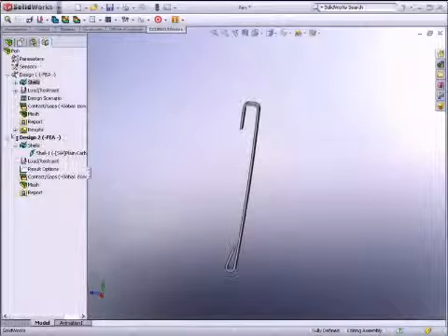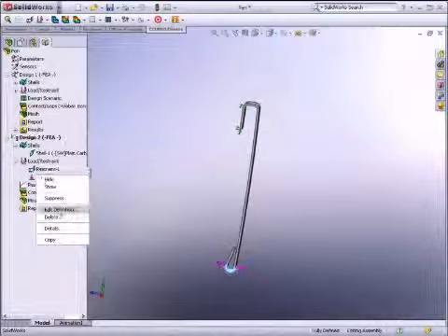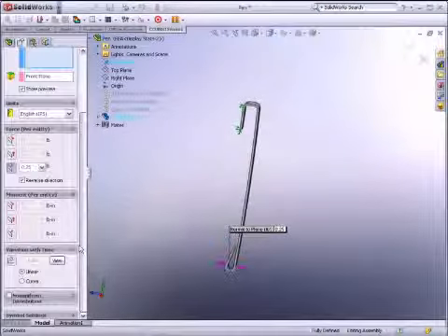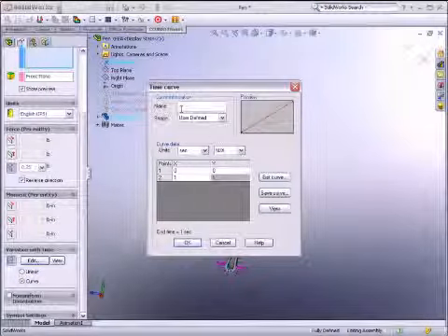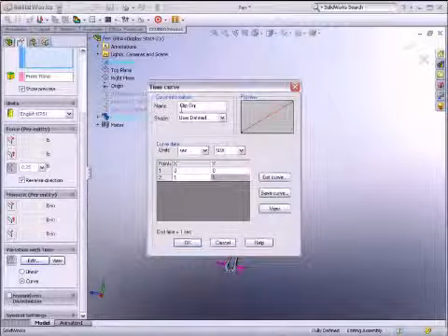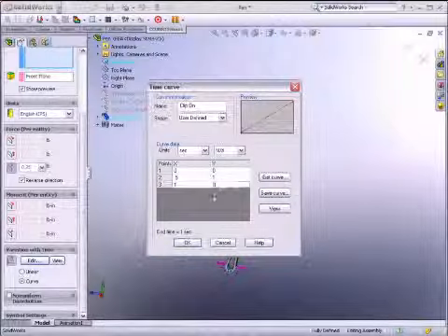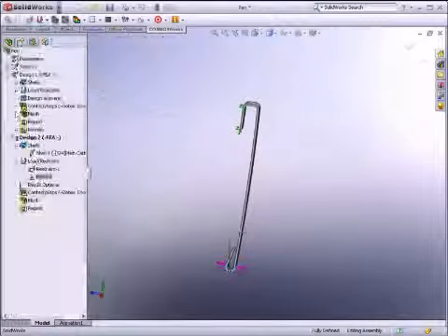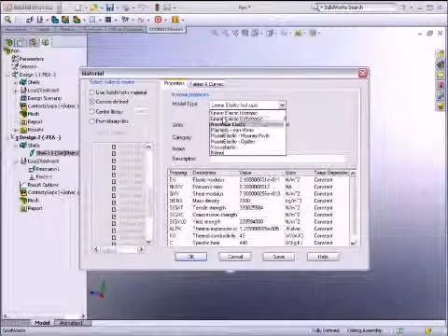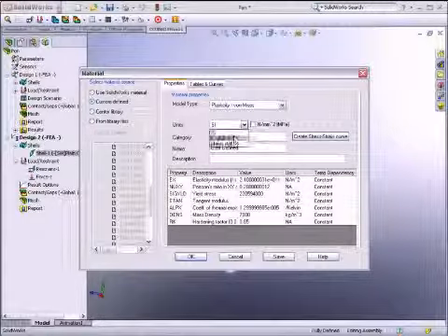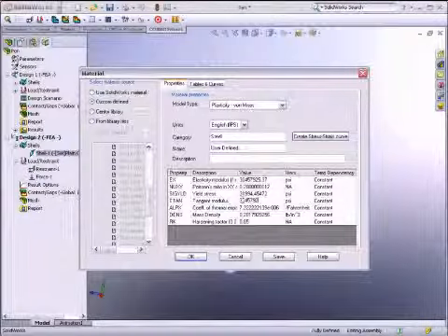With SolidWorks Simulation, you can simply copy the shells, loads, and restraints, saving time and ensuring consistency. We can also easily modify the load condition so it varies over time using the curve option. In this example, we will create a simple curve that represents the load applied. This will allow you to see the deflection after the load is released from the model. In this case, we must define a custom material and specify the tangent modulus that is not given in the default material properties.